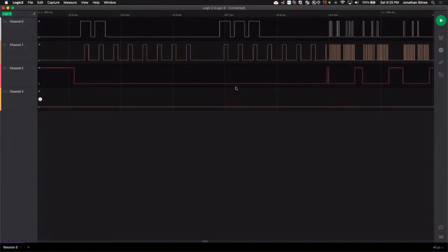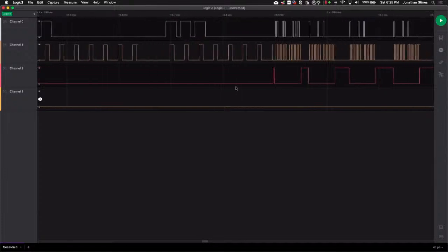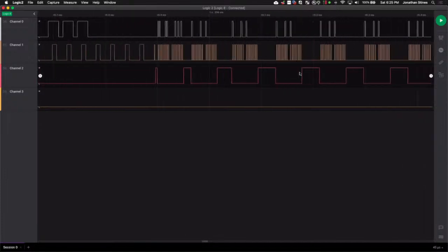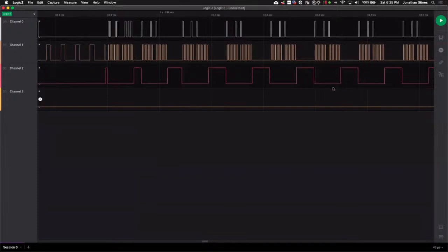And then enable. Say for instance there's 3 slaves communicating with the actual master node. The enable will flip the bit for when that device can communicate or not. You'll often see, and there might be a little bit of a mismatch in our timing, which we can also fix, that with the enable, right here, there's basically 3 ones.